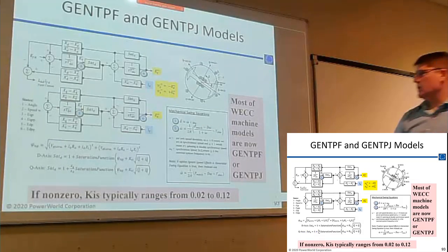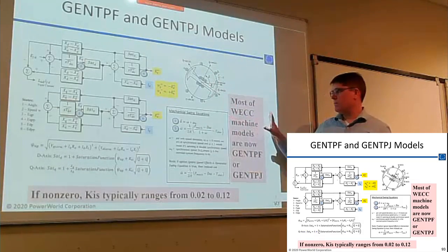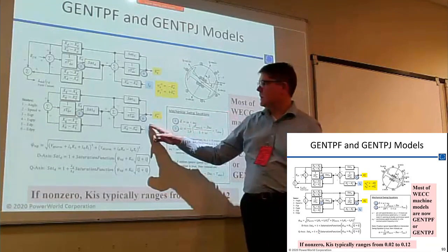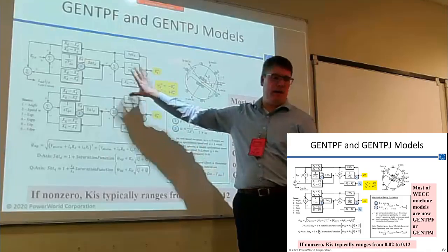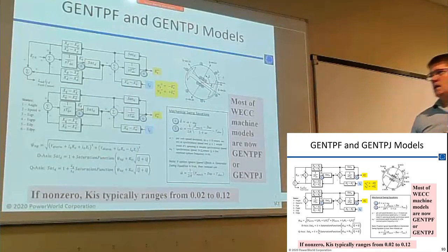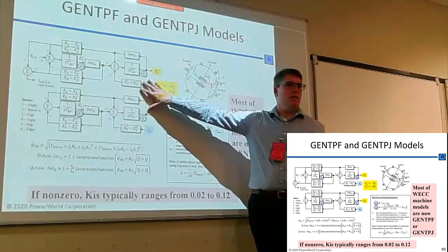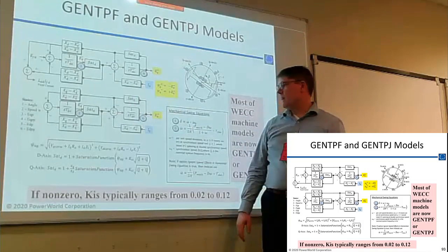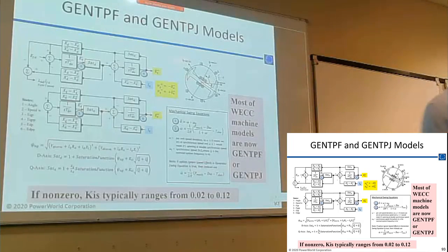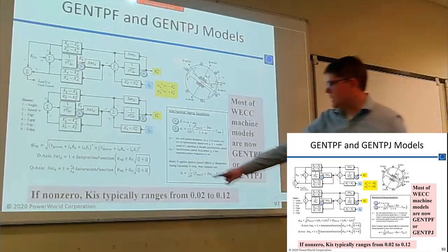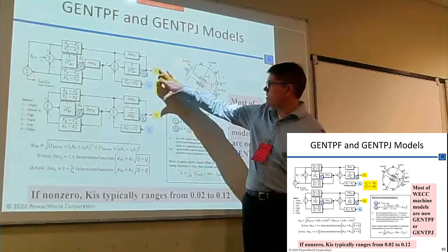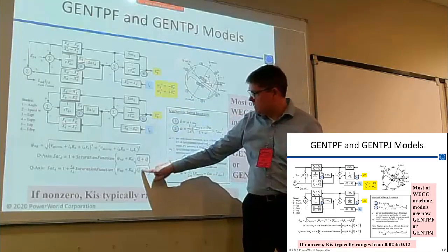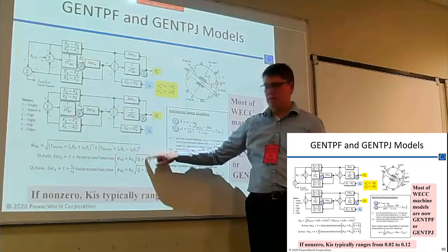A lot of the models in WEC are like this. One of the things with the model is, if you look at the block diagram for this model, the leakage reactance is not in there. So I think somewhat unintentionally, they made an approximation in the differential equations that later on we found maybe we didn't need to make. But the big change is right down here: the saturation function itself is no longer just a function of the voltage, but also a function of the terminal current, the stator current. So as the machine is loaded, the saturation changes.